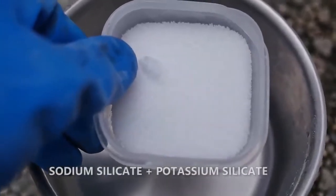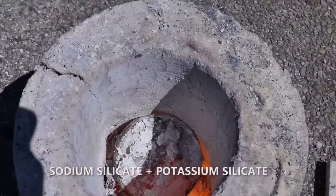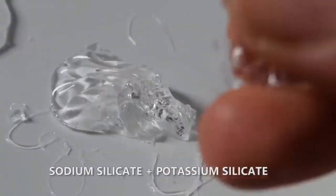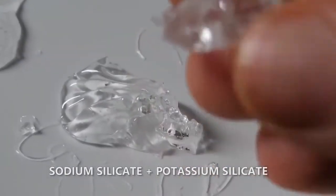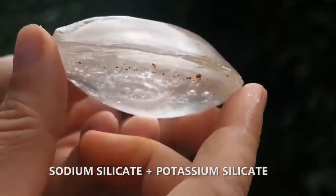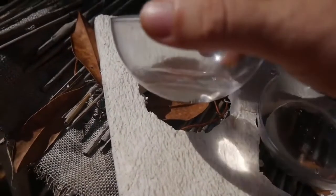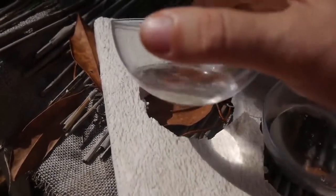Natron mixed with lime gives caustic soda. Caustic soda mixed with water and white sand heated to 1000 degrees Celsius produces sodium silicate, referred to as liquid glass or water glass. They mixed it with potassium silicate, obtained by the same process. They poured the liquid into a lens-shaped mold. 2 to 3 days later, they unmolded the transparent lens.